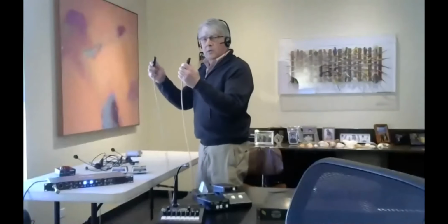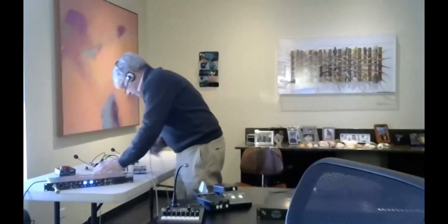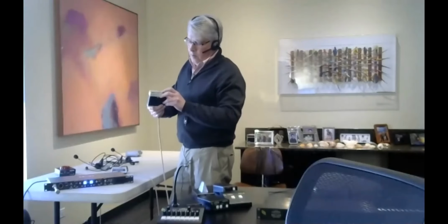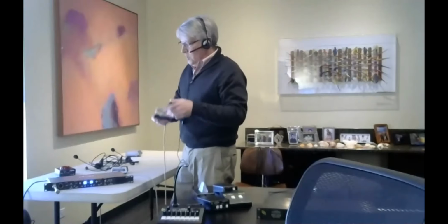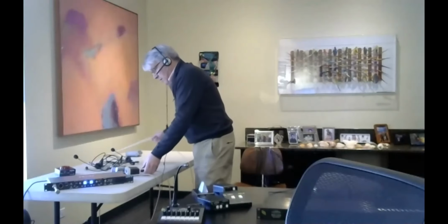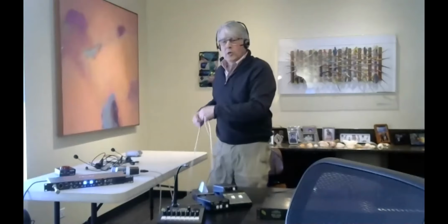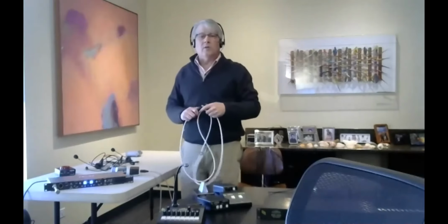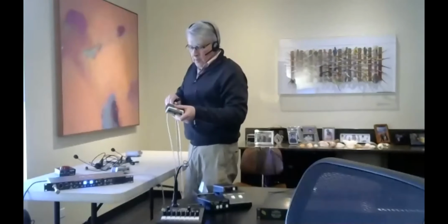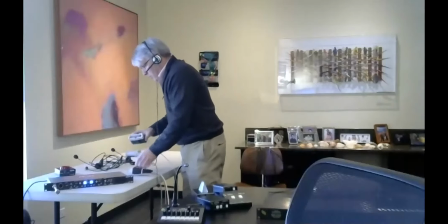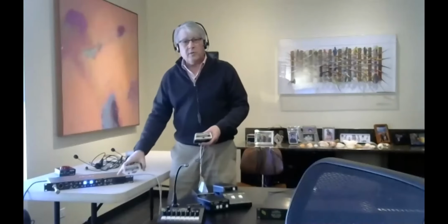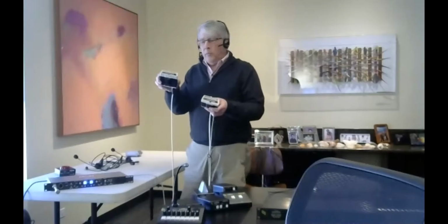What does it take to do this? I take an XLR cable. I plug it into one of the outputs. I connect it up. And the belt pack is now working. Now you have a master station and one single channel belt pack. And now you said, okay, I have 2 camera operators because I'm at a junior college and we're going to have 2 cameras to do an event. So all you have to do is take the loop through connector, connect that up, go to your next belt pack, and you're done. Now you have a Partyline, right? You've got a master station and you've got 2 belt packs.